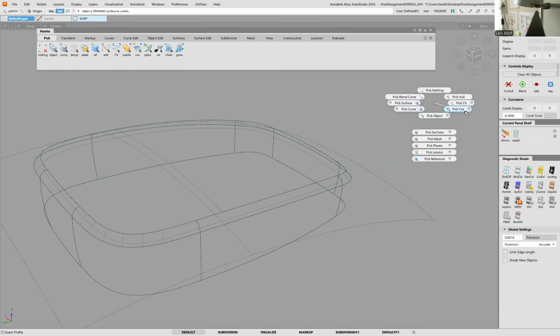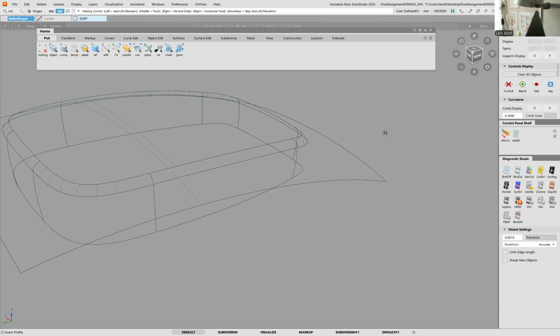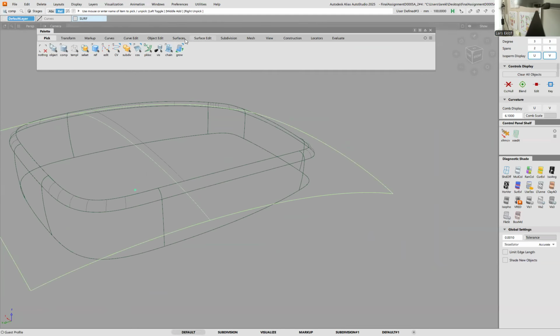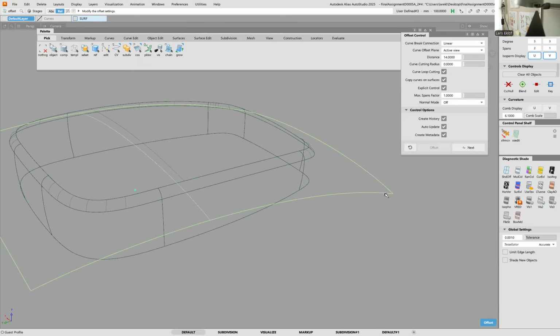Get rid of our curved surface on this big one here. And once I've done that, again, offset it. So I pick that surface and once more offset, but this time only the gap size, which was, I believe, 2 millimeters.